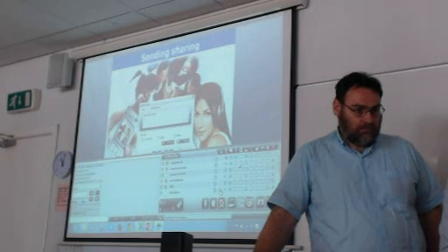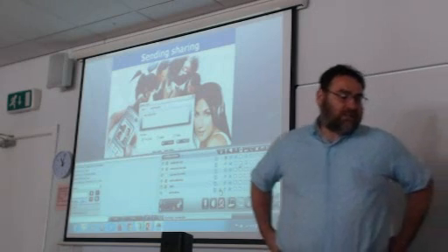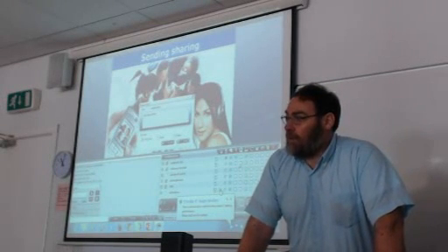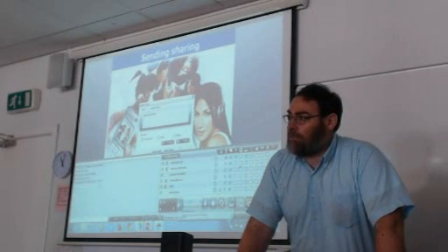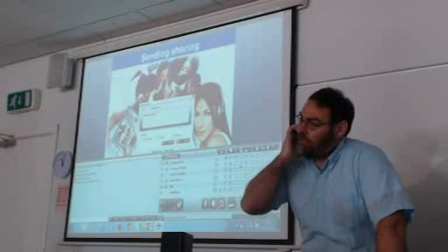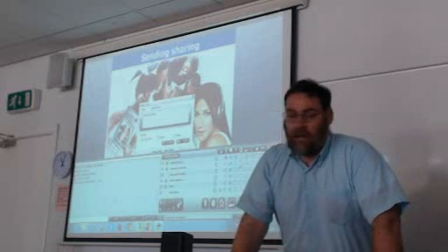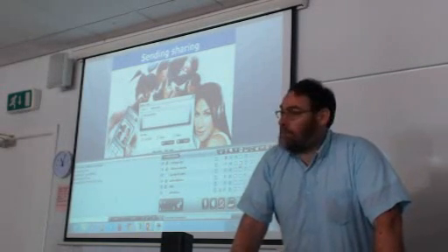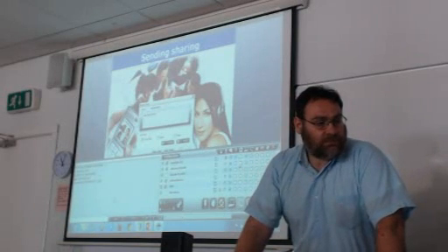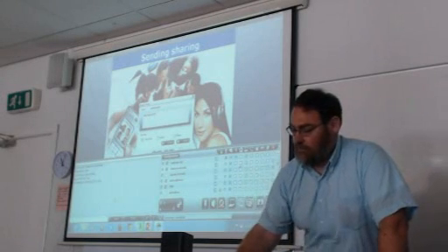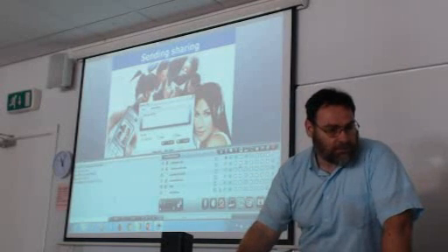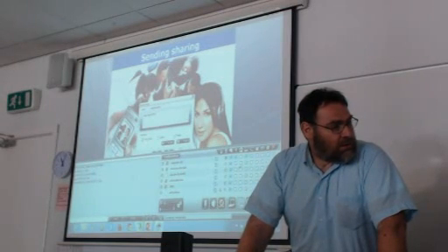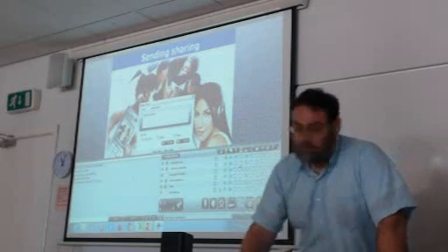Any other question? We can see if we have any questions. Yes, I saw a raised hand. Could be. Pilot fuel is liquid, certainly liquid. The question is if pilot fuel is heavy fuel oil. Usually marine gas oil or marine diesel oil is used, or low sulfur marine gas oil is used within ECA, emission control areas. But yes, heavy fuel can be used as pilot fuel.